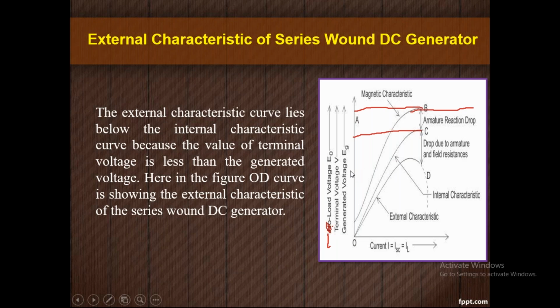This is the value we can apply as the terminal voltage. Okay, when the field resistance is more than the critical resistance, then the generator comes to rest position, which is indicated by the dotted lines here.